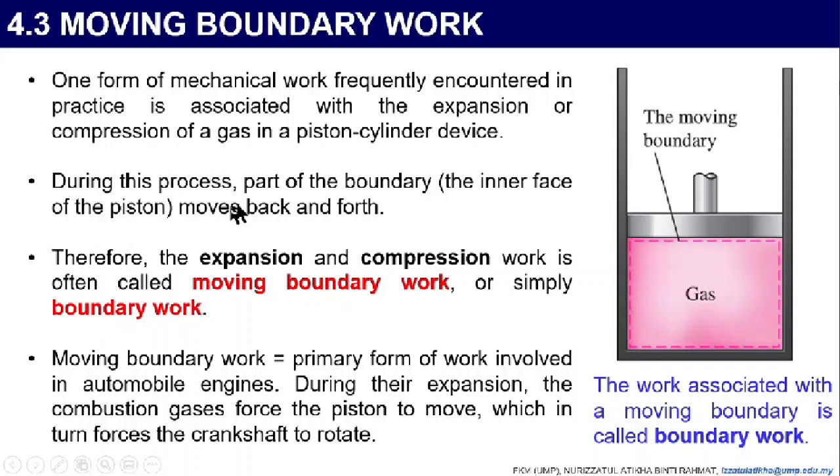During this process, part of the boundary, the inner face of the piston, moves back and forth. Therefore, the expansion and compression work is often called moving boundary work or simply boundary work. Okay, this process where the expansion and compression work happen is called moving boundary work or simply boundary work.